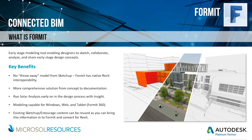However, as anyone who has ever used SketchUp knows, those models have never really translated very well into Revit once ready for documentation. And that's mainly due to the geometries and meshes that don't jive well with Revit all the time. So enter FormIt. And although FormIt has been around for a couple years, it has recently evolved quite considerably and now can be quite useful in the conceptual and schematic design phases. Most importantly, it has native Revit interoperability, so we no longer have a throwaway model from SketchUp or another platform that are either too difficult to import into Revit or so cumbersome that we just have to start over with Revit.